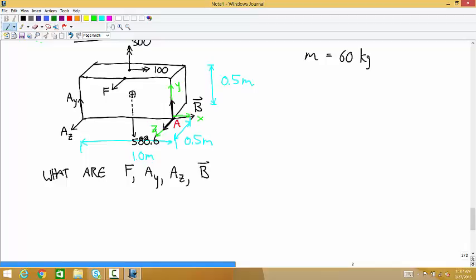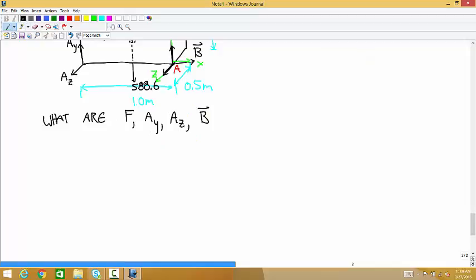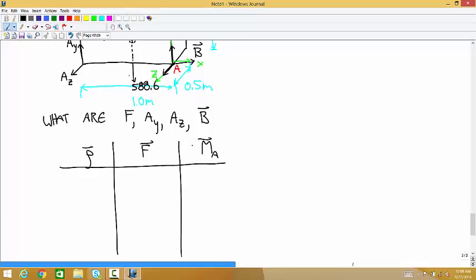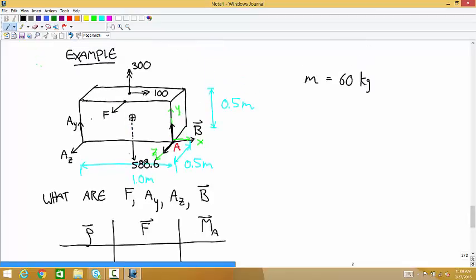Is there a joint to this? No, so basically I've already taken the step in this problem of taking the joints and expressing them as loads. So this would have been a joint, and this would have been a joint, and this would have been a joint. Okay, but I've already taken that step, so first we can just see the math work. Okay, so let's calculate the row vector, calculate the force vector, calculate the moment. And we're going to do this one by one for each load.